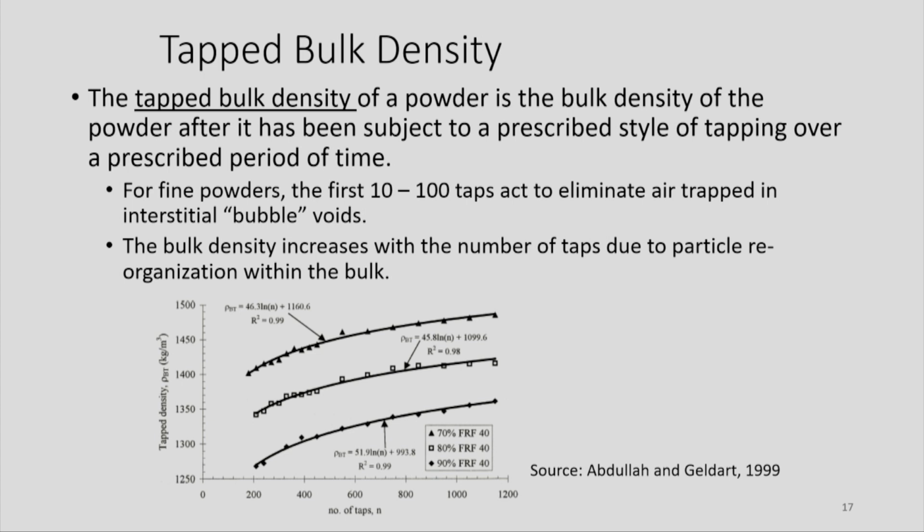Tapped bulk density, you all know tapped bulk density, right? You tap it for some amount of time and then calculate the change in volume after tapping. One of the major challenges is how many taps you should do. You don't know, right? Sometimes with the number of taps, the volume keeps on changing. But there are many standards that give an optimum number of taps you have to do. Okay. How many of you measured tap density?